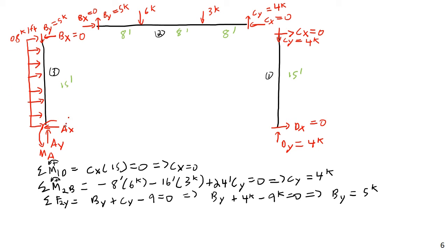Then, looking at this beam here, or this column here, well, it's a beam column. Again, in structural engineering parlance, anything that has a bending on it is going to be a beam. So this thing has horizontal loads, or transverse loads would be a better way of stating that. So yes, this is actually both a beam and a column, but usually we still refer to things that are vertical as a column, so I'm being a bit sloppy with my language. But anyway, I just see loads like that. I'm like, oh, that's a beam.